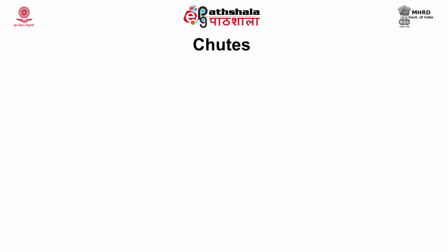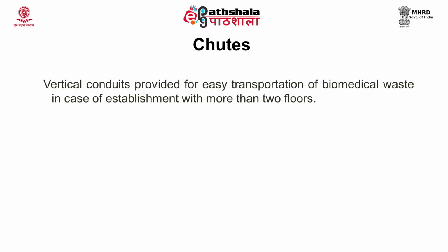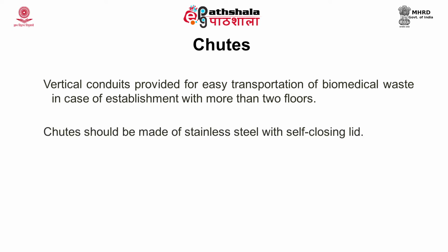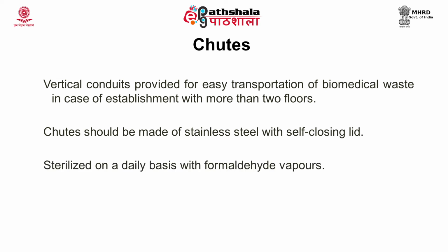Now, chutes. Chutes are special type of conduits. They are vertical conduits provided for easy transportation of biomedical waste in case of establishments with more than 2 floors. Chutes can be made of stainless steel with a self-closing lid. The chutes should be sterilized every day with formaldehyde gas.